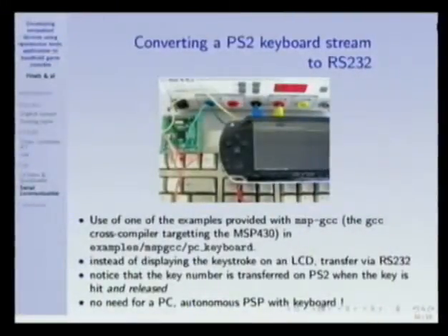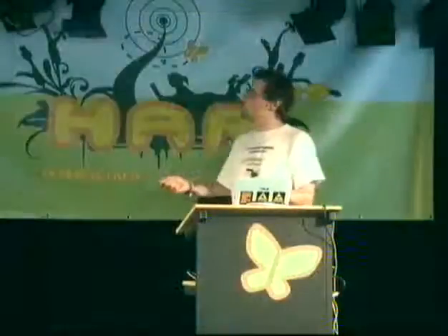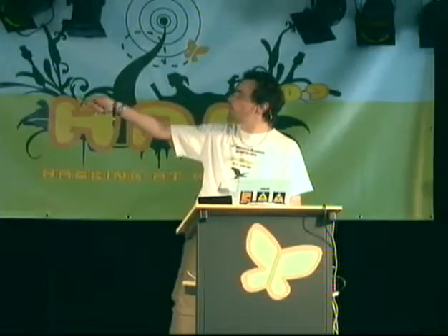So basically on the PSP, you have your piece of software, you have Linux running, but since you have no hardware available, because I should emphasize that there has been no, to my knowledge, successful reverse engineering of the Wi-Fi link or the USB link on the PSP, basically the only thing you can do nowadays is have an external microcontroller for all the dedicated hardware access and send or read commands through the RS-232